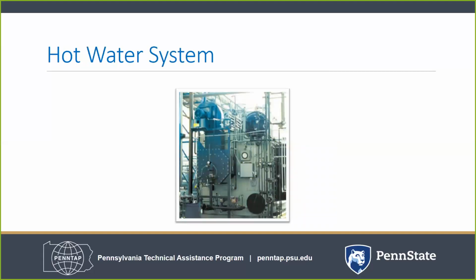Hot water systems. If you have a boiler system, think about combustion efficiency. Adjust the combustion system air-fuel ratio. Keep insulation in place and in good condition. Repair steam leaks and traps. Take advantage of wasted heat.